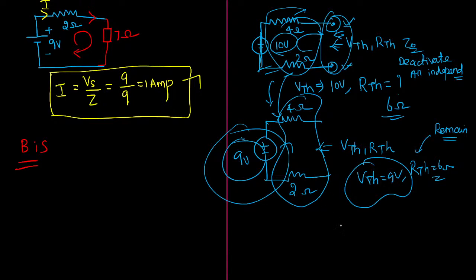Whenever we are considering a linear bilateral network, while changing the input voltage for the network, what will happen? Thevenin voltage might change, but the Thevenin resistance will remain fixed. If they change the value of input voltage, Thevenin voltage will keep on changing.